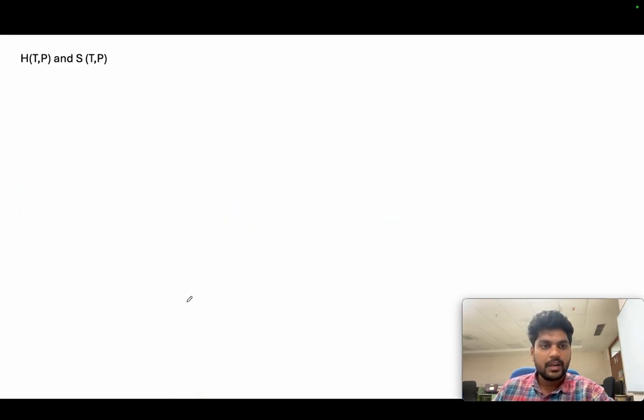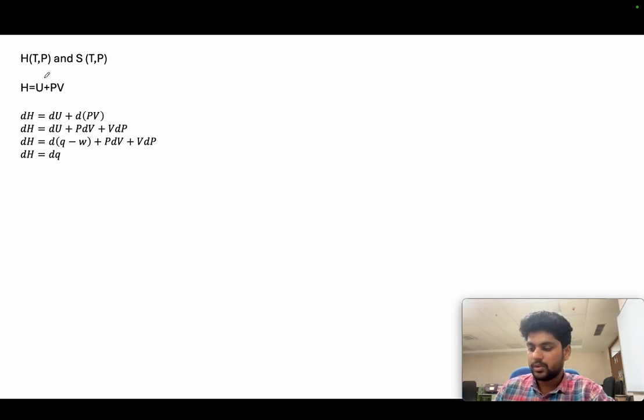So the best way, which we have done in the last classes also, is this: we know that H equal to U plus PV. I think you have it in the third week assignment problems also. It will be better to understand this. H equal to U plus PV. I did the differentiation. dH equal to dU plus d(PV). For this component, I have applied the chain rule. dH equal to dU plus PdV plus VdP.